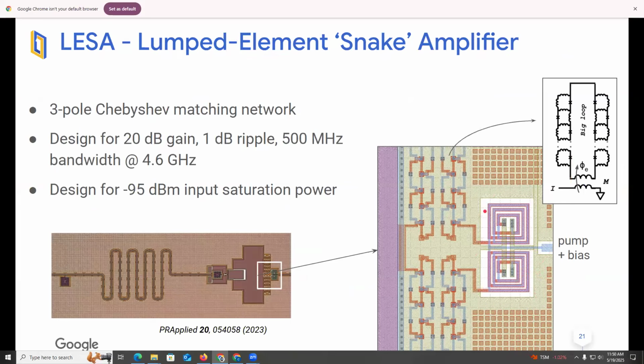Which ground plane holes? These are not holes. No. So actually, this is a multi-layer process. So these are just fill shapes to get the edge to not being too dependent on our design. There's no ground plane, so there's no ground. The hole that you see is here. So there's a hole around this just because you want that mutual inductance to be large. So you remove the ground plane underneath.